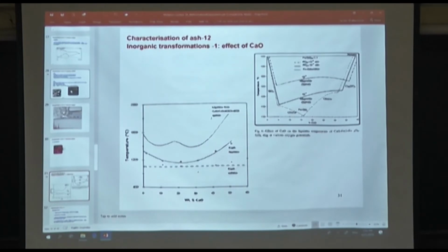The software also will tell you in this zone between that calcium oxide level and this calcium oxide level, you will be getting the magnesite, the spinel structured magnesite. And then you look at the database, and then you find out what temperature it melts. Your sample must have experienced that temperature, otherwise it would not have predicted that particular compound.